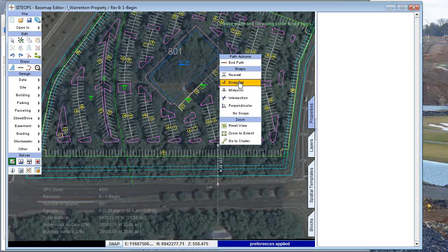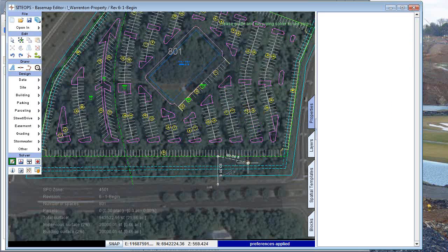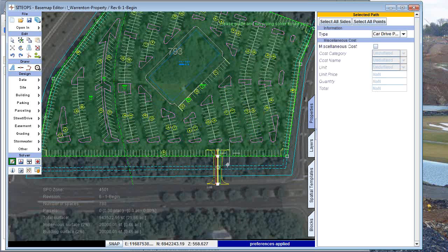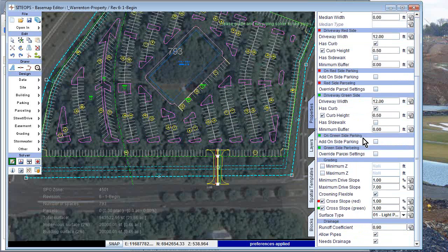And you'll notice I also have snaps to make it accurate. So perpendicular would many times make sense. So we have a perpendicular entrance now. When I look at the properties for that road, I would normally change these in production, so I don't have to change them. However, when I do presentations, I leave certain settings incorrect just to show you that I can correct them. So I don't want a flexible crown on this road. I want a normal standard 2% crown, and there we go.